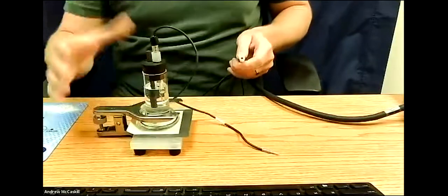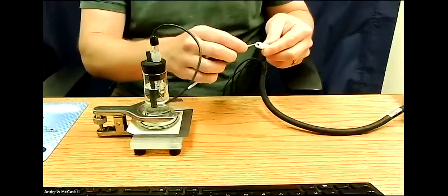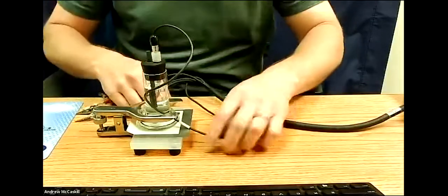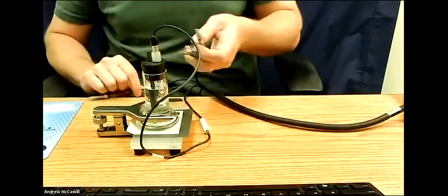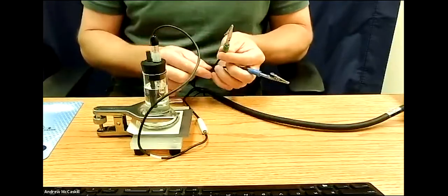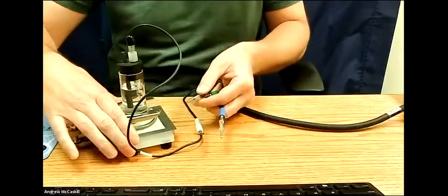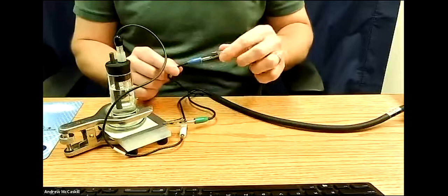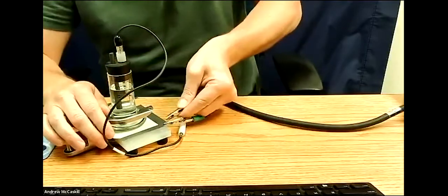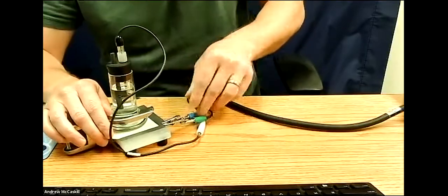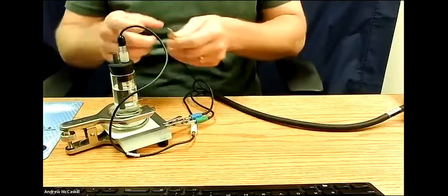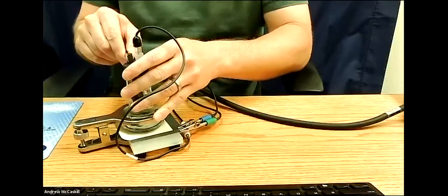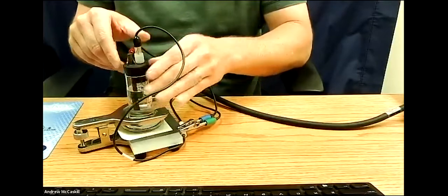So in terms of connections, for our cables, this white lead will accept the plug for the reference electrode. You have your green current carrying cable that you're going to connect to your working electrode, which is going to be the sample. Same with your working sense cable. That's also going to be connected here to our working electrode, which is our sample. And then we only have left the red counter electrode, which I'm going to connect here to the graphite rod.